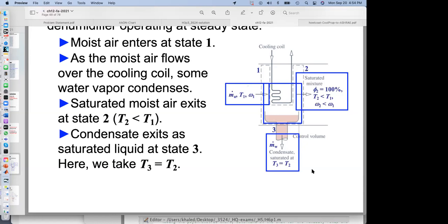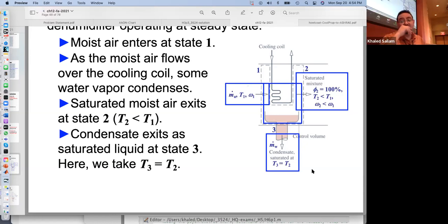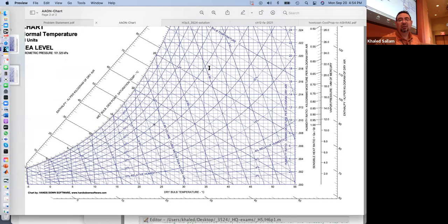Because it loses heat when it condenses. Well, yeah, it loses heat, but I mean, it doesn't condense at a different temperature than the air from this chart. We are at 35 and 60, and then we get cooled like this, and because the air is leaving at 20, the water is also condensing at 20. Why would the water have a different temperature than the exit air?